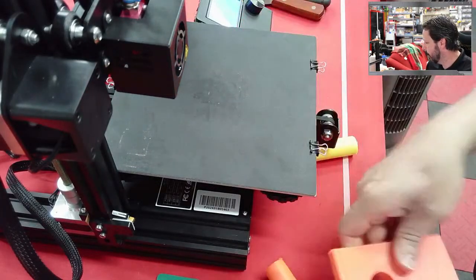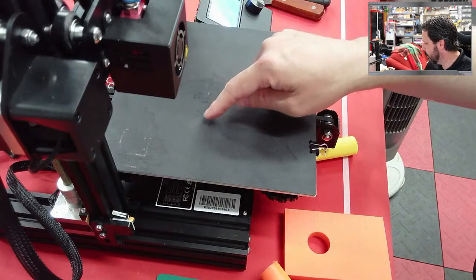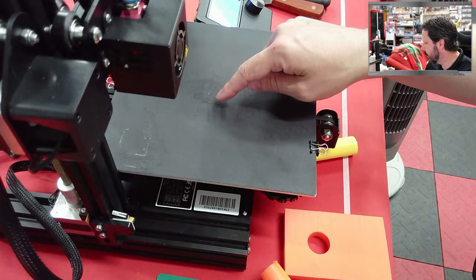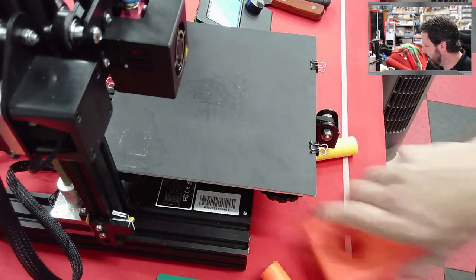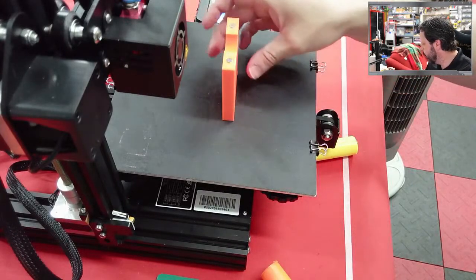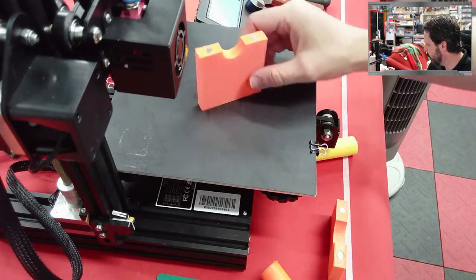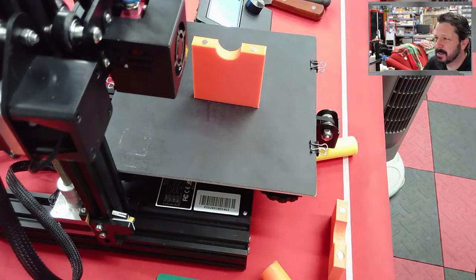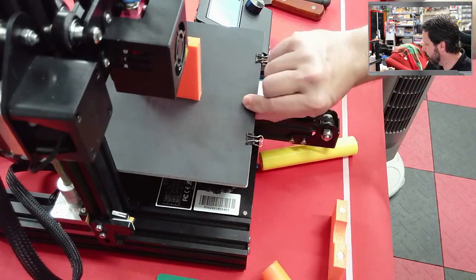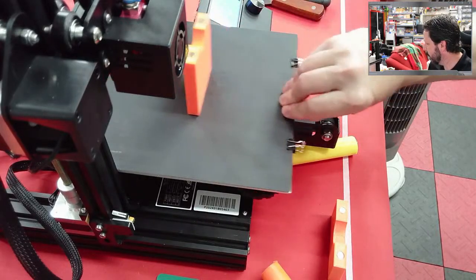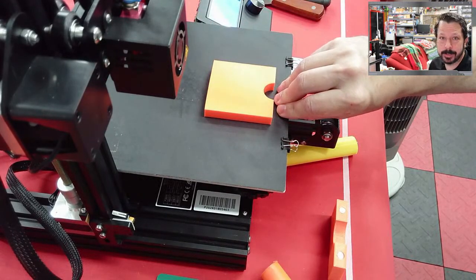So that means what was happening was this side of the bed was just a little bit lower than over here, and it didn't stick as well. Now I print this part this way. For tall parts that are shaped anything similar to this, it would actually be better to print it this way, because, and I didn't, and it was fine, but this bed moves back and forth, right? And so for parts that are shaped like this, that moving back and forth is going to make it want to do something like that.